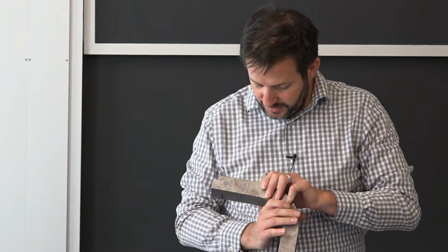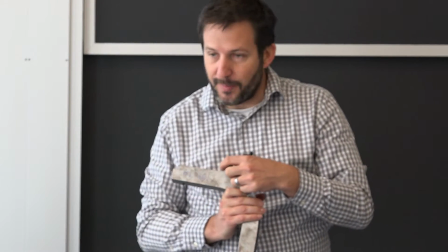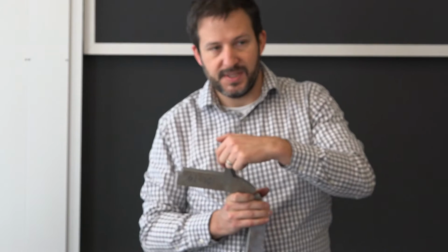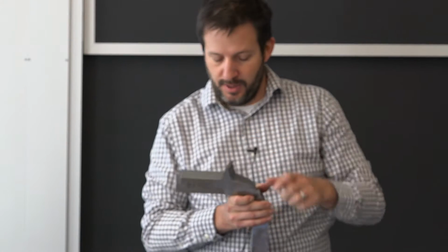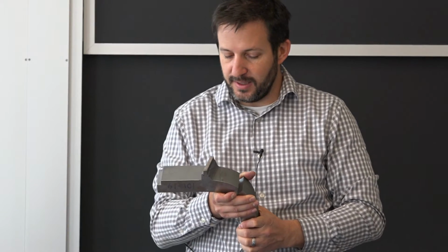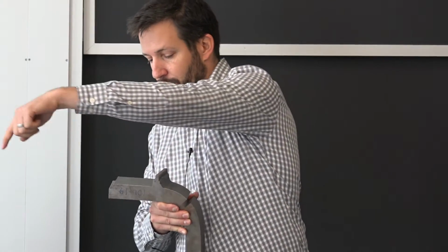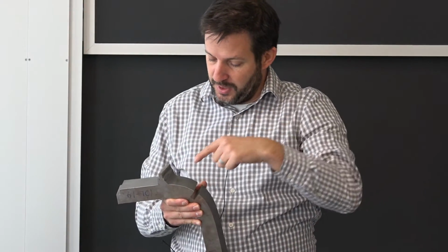What you'll see on the sample, there are a couple of other features. There's a little bit of what we call a backup bar of steel behind the wall here, and that is to facilitate getting a good root of the weld. So you weld from the outside on these. The tube is over here, and you weld from this side.